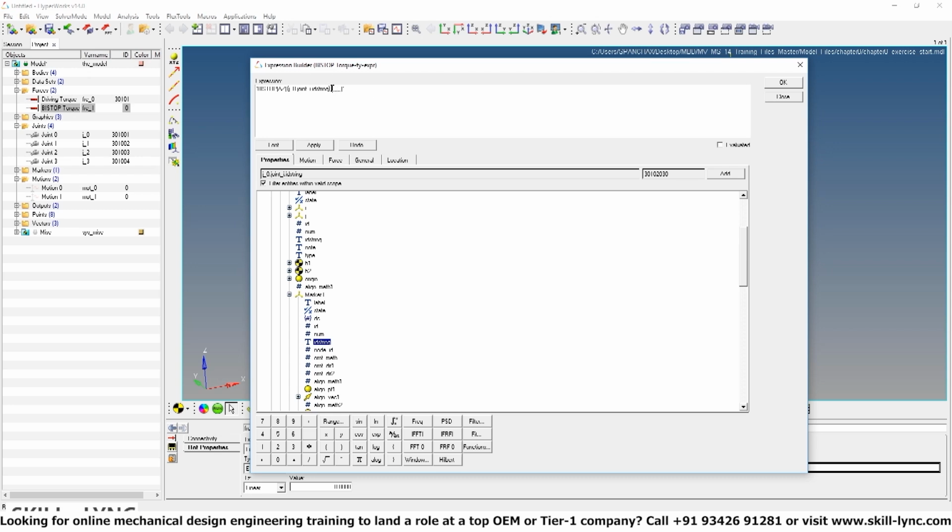You can come to the place which is after the comma, and here let's select the ID string of the J marker. So you minimize this, you expand marker J and select its ID string and say add. Okay, so this gets done. Once this is done, you can go ahead and put this in the curly braces. So this should be in the curly braces and it should be closed with this close parenthesis.